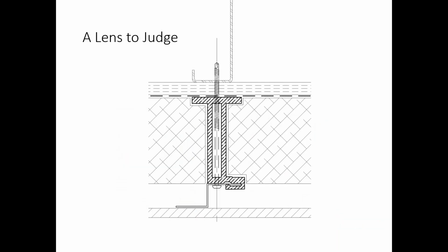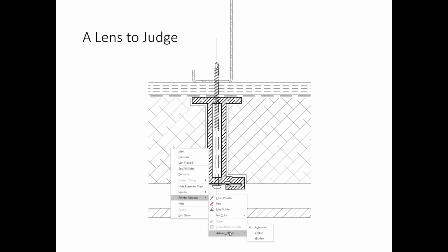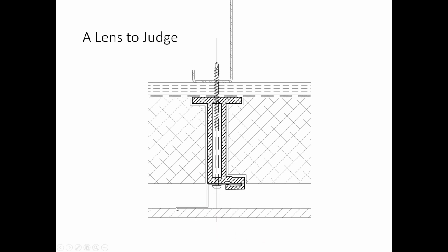So I'm going to leave cladding now with a lens through which I would suggest that anybody on the call evaluates the fire safety by observation characteristics of cladding supports. And what you're looking for is non-combustible connections, in my opinion. So if you trace this detail, which has the exterior cladding on the bottom of the screen, and you trace, I'm just going to make sure that my pointer is actually visible to everyone. If you trace along that metal cladding support to the metal screw, continuous metal screw all the way to the metal stud, you could do that on a piece of paper without lifting your pen.